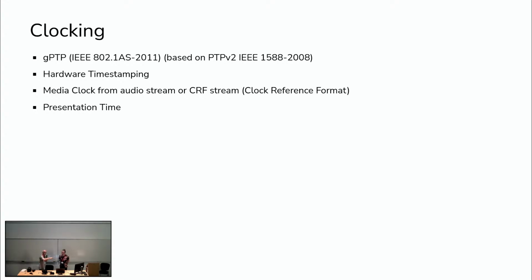So all the sources and destinations are synchronized by this universal time code, which is handled by gPTP or Linux PTP. In addition to that, you need what's called a media clock, which is what's going to clock the samples out or in of A to D or D to A interfaces. That clock is not handled by gPTP. It has to be derived from that somehow. And so you have to have that distinction in mind when you think about time within AVB.